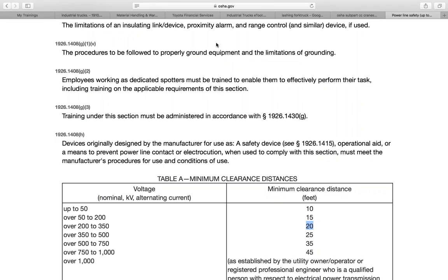Okay, so there are all your different hazards, and then ultimately the last one is we have to be responsible to know what kind of underground utilities, right, as far as gas, oil, electric, telephone lines, sewage, anything that's underneath the crane. Now, this is one of those circumstances where the OSHA standard says that the host facility or the host employer shall verify all underground utilities and ground conditions, and advise the crane company and the operator. But the OSHA standard also, right here in the crane standard, says that we as crane operators or the employer must also verify that those reports are correct.